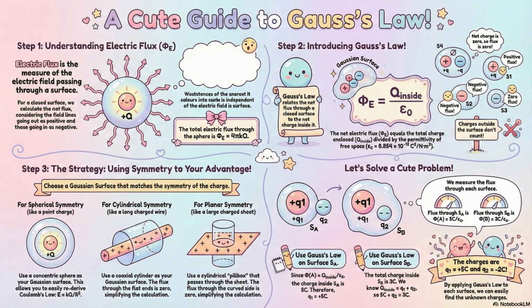So if I have a material with a dielectric constant of 10, the force between two charges inside it is literally 1/10 of what it would be in the air. The material is kind of shielding the charges from each other. It is. And that ability to suppress or contain the field is absolutely critical. That is exactly what allows us to store charge efficiently in capacitors.